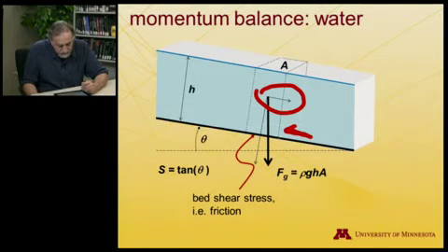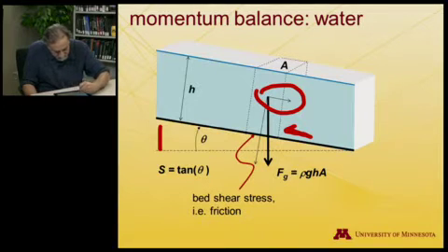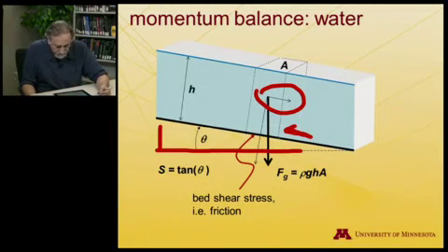So we're going to use the slope. The slope is the tangent of this slope angle, but the slope for a river is normally given not as an angle in degrees, but as an actual tangent value, which would be the rise over the run. So the slope, as usually reported in a river, would be this distance relative to this distance, so the tangent. And oftentimes it's given as a percentage, which is a common way to express non-dimensional ratios like that.